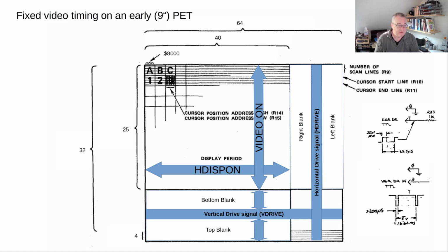In this schematic, the video output has to read the actual character value, say A for A, hex or 65, I think, 66, 62, and so on from memory, and then select one of 8 rows in the character ROM, one for each of those raster lines per character.